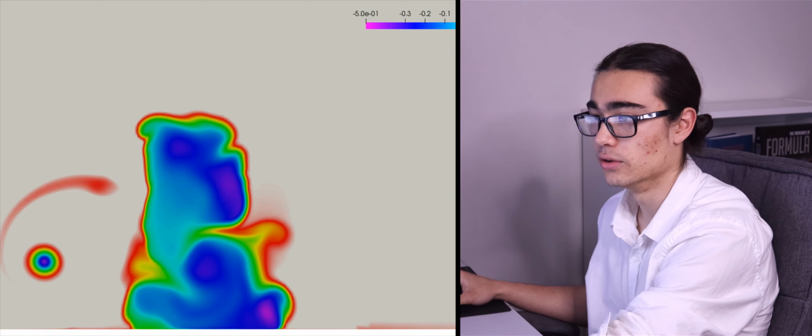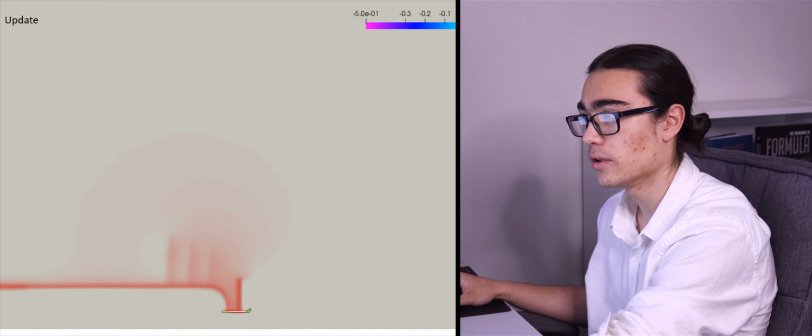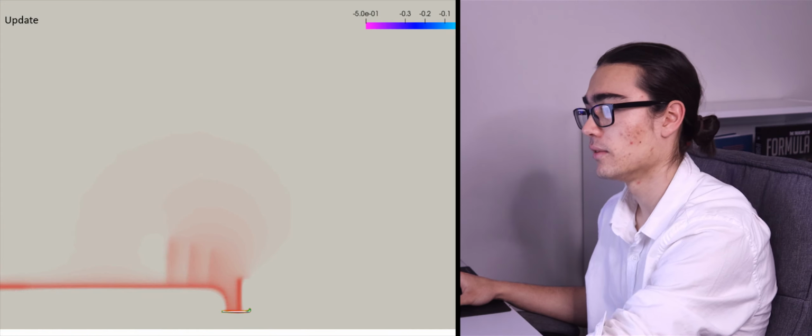Okay. Now let's have a look quickly at a brief overview of our updated case. So firstly, we've already got a little bit of a blow here, which is unfortunate. However, we'll still see some of the effects. Now we're also generating a vortex off the canard. This is an edge without an end fence on it, so it's very easy for the air to loop around, and we're going to generate quite a powerful little vortex here.